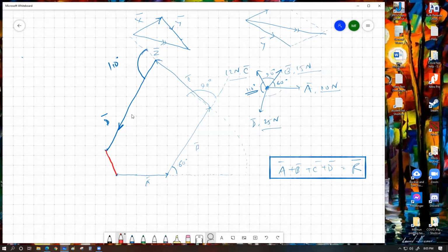And the direction of the resultant should be reverse compared to the component direction. So in this case, you can see that the components have their direction aligned in a sort of anti-clockwise rotational direction. So the resultant should be working this way, pretty much like the triangle rule. Like you see that the resultant for the triangle rule started from the first vector and finished up at the end point of the last vector.